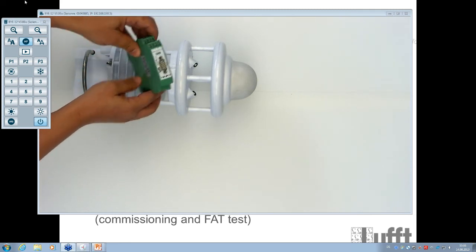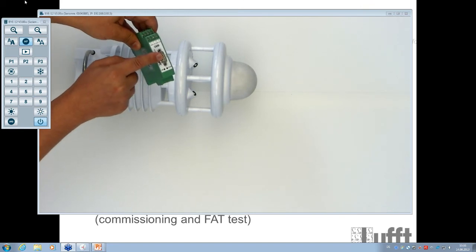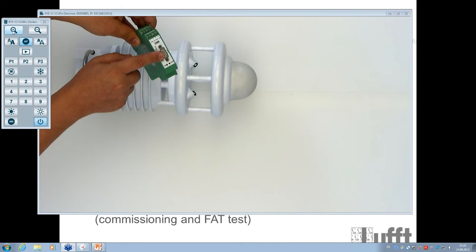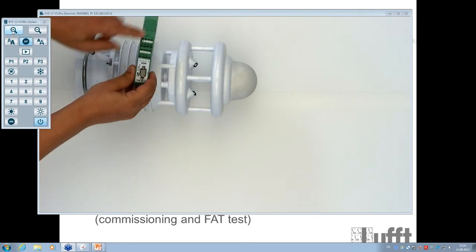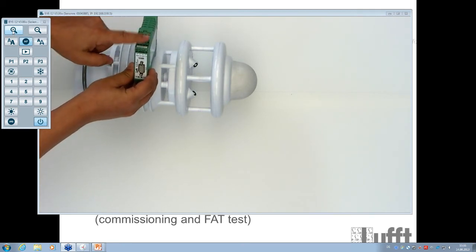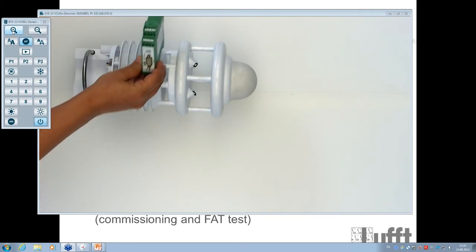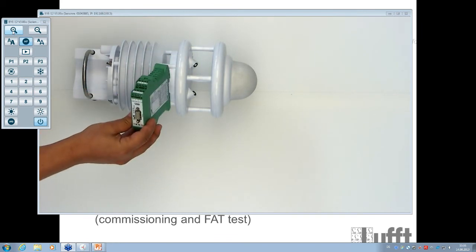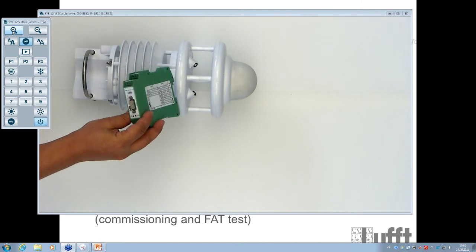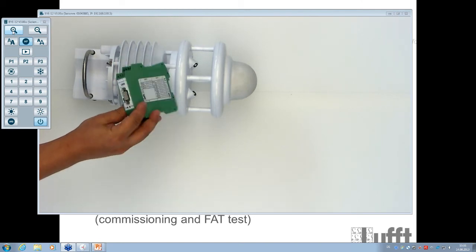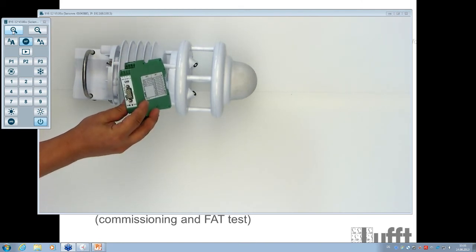So the ISOCON has one RS-232 port, so you will be able to connect some modems, GPS modems, or COM servers or something like that, right? And you have two connectors here to connect the WS sensor directly to the ISOCON. This ISOCON normally is a converter which converts the original RS-485 signal of the WS into RS-232.